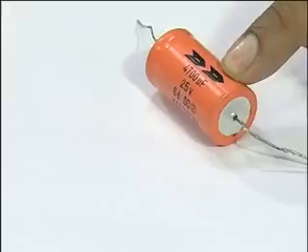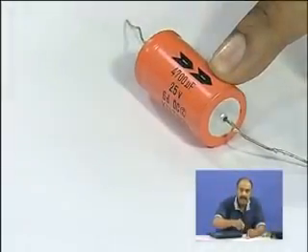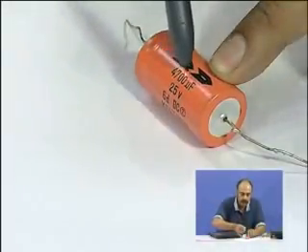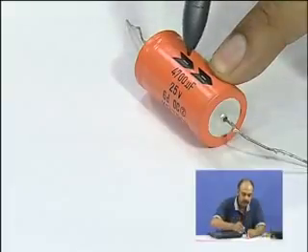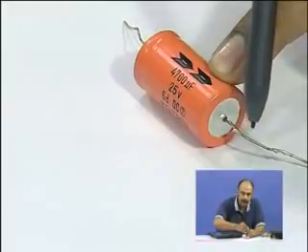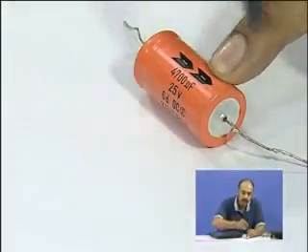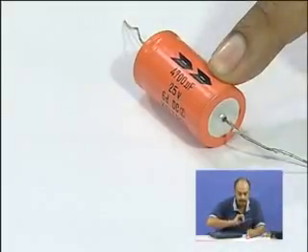With some marking here. Now, this capacitor has leads on this side. This is an axial lead capacitor. It is 4700 microfarad capacity value. You see the minus sign here with an arrow sign, which means this lead is negative, which means the other lead should be more positive than this at every instant of time. So, this is a polarized capacitor.